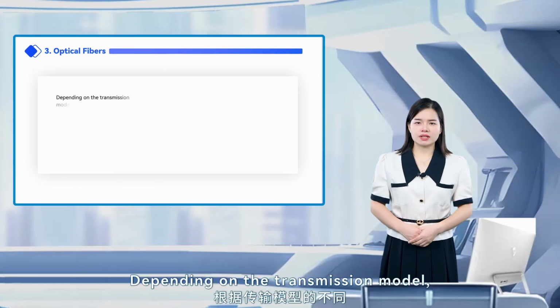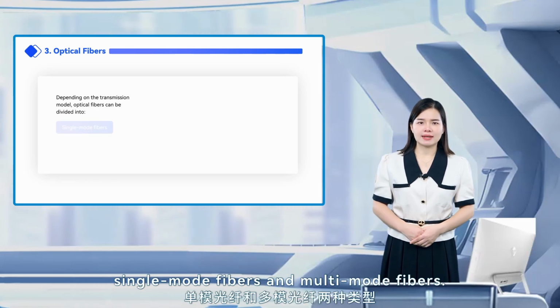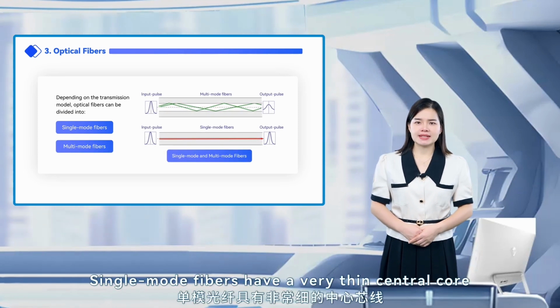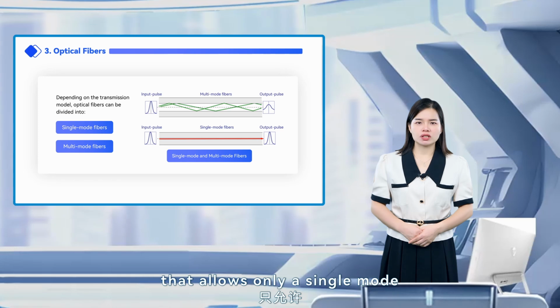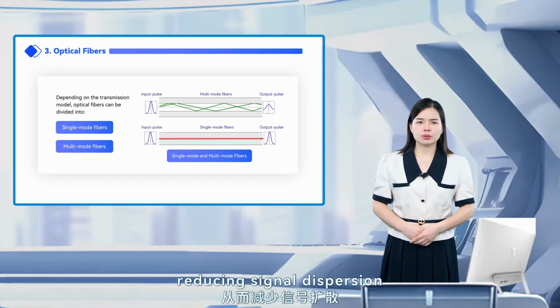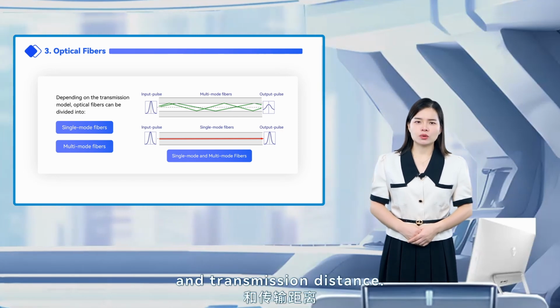Depending on the transmission model, optical fibers are primarily divided into 2 types: single-mode fibers and multimode fibers. Single-mode fibers have a very thin central core that allows only a single mode of light wave transmission, reducing signal dispersion and significantly enhancing bandwidth and transmission distance.